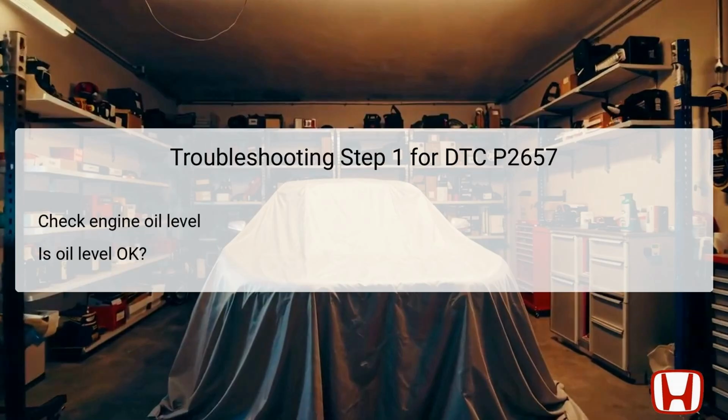The first step in troubleshooting the P2657 code involves checking the engine oil level. Low oil levels can significantly affect the operation of the rocker arm oil pressure switch, leading to inaccurate pressure readings. Ensure that the oil is filled to the recommended level, as outlined in the vehicle's owner manual.